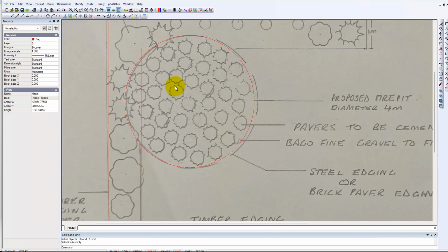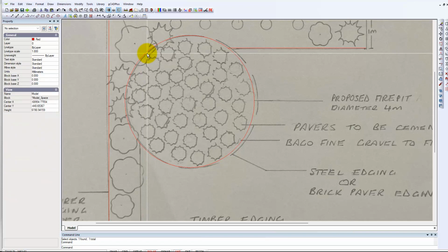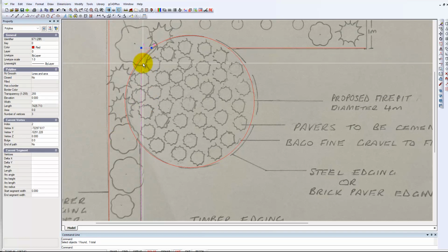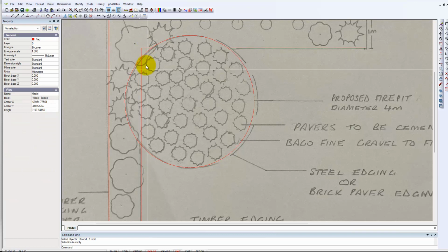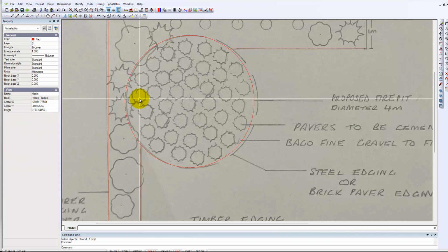The trim action didn't go quite to plan, it cut off the section through there, but if I select here, notice there's a small line through there, so we just hit the delete key on the keyboard, and that failed because, you remember, it was joined. The easiest way to do it is to pick the trim command again, pick the cutting edge, and then remove the errant bit. We're then left with these two short segments, so we just delete those.